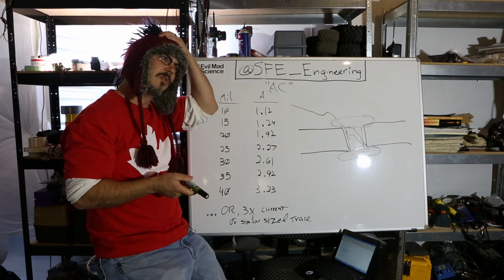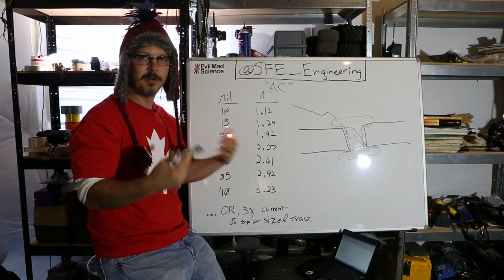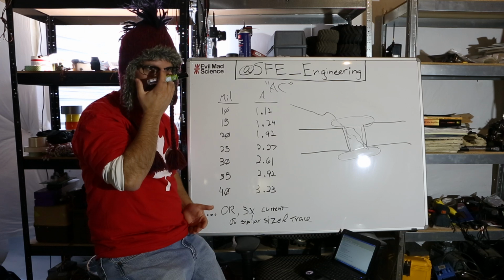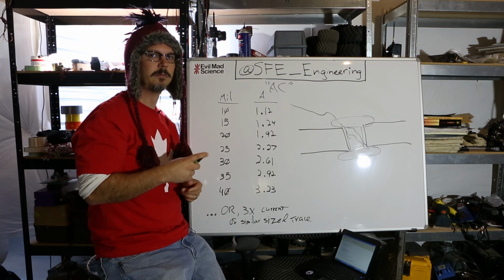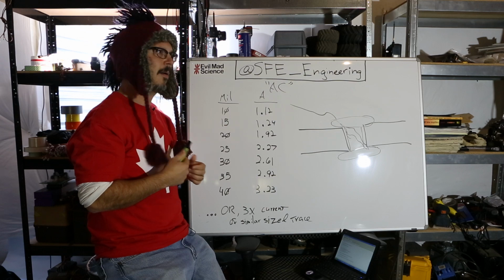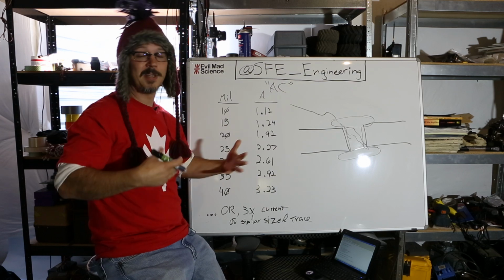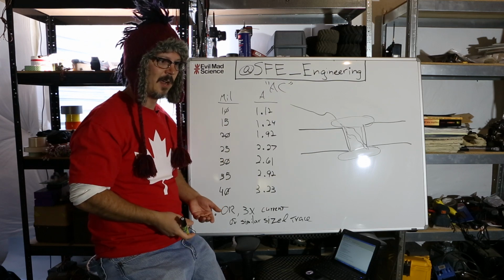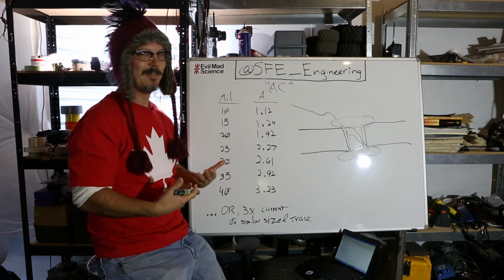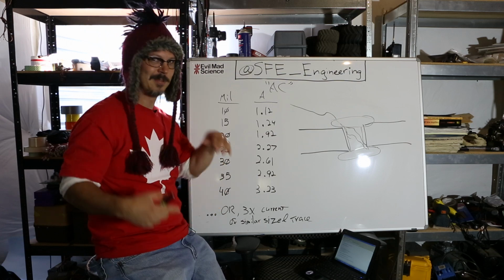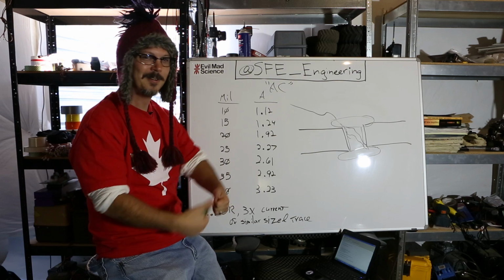One last point that I will make is that in our own designs, SparkFun designs, we rarely go below a 20 mil drill hit for a via. We do sometimes when a design calls for it, but we usually like to have a lot of forgiveness in those sorts of things. So we like to have big vias. We like to make sure it's a low impedance. We like to make sure we've got really good continuity.